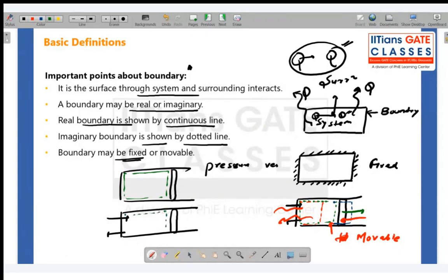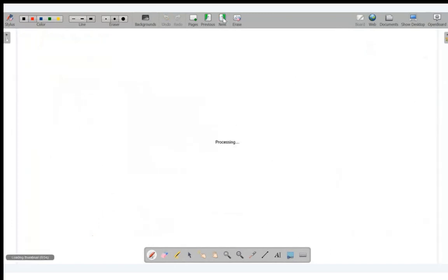and this is your piston. Right now this is your boundary. But let's say fluid is coming in, so this piston is going to move forward. So you see, this line is going to change, so the boundary is increased. If fluid is coming out, then the piston is going to move in the opposite direction, so this boundary is going to reduce. You see, the green line is moving in this direction. Earlier it was moving in the forward direction. So now the boundary is changing. So this is called a flexible boundary. Okay, let's move ahead.